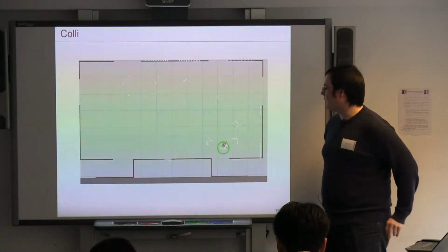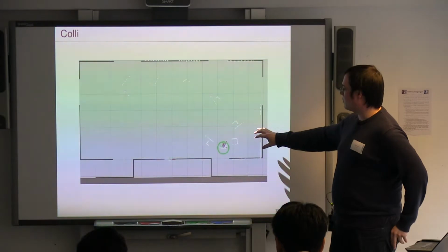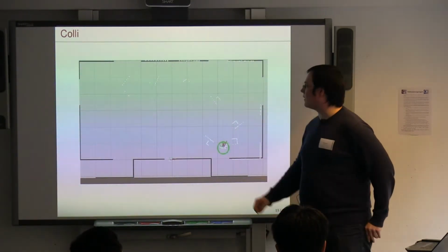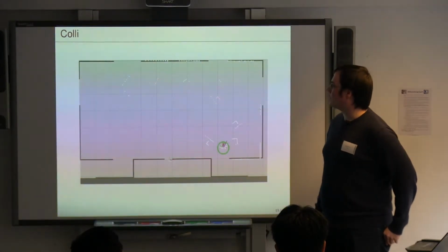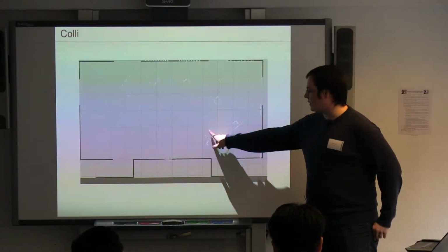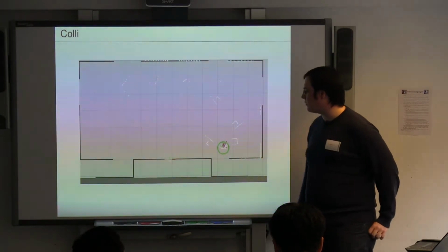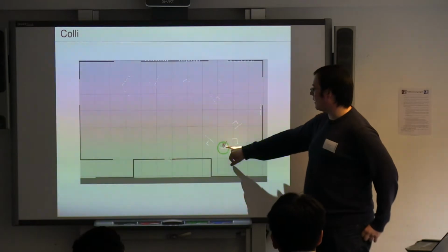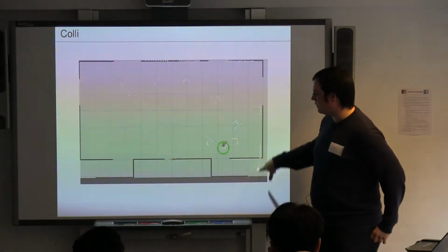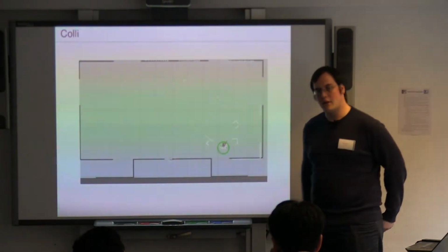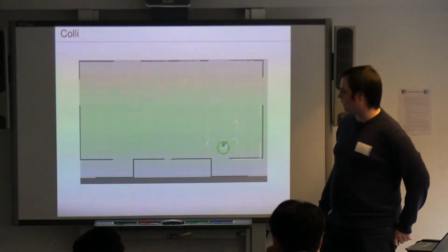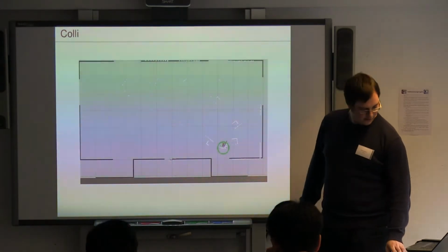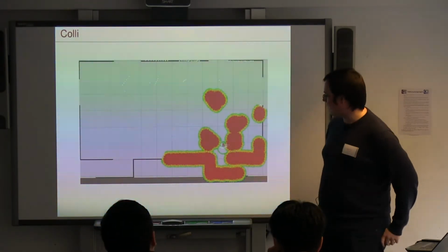So first of all, how it looks for the robot. Well, the robot is here, and for this path planner, we're using the laser data to calculate obstacles and a grid. The grid you can't see here. You can just imagine a grid around the robot, with 5 centimeter distance, where the obstacles are inserted. So you have this laser data and then the obstacles, and this would look like that then.